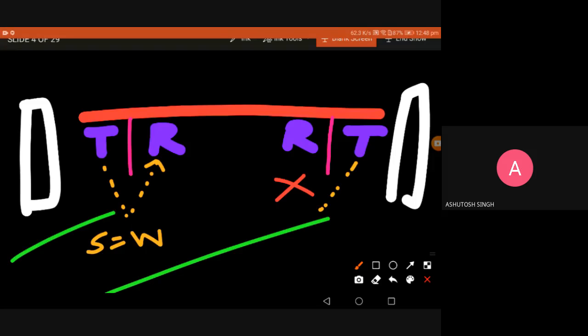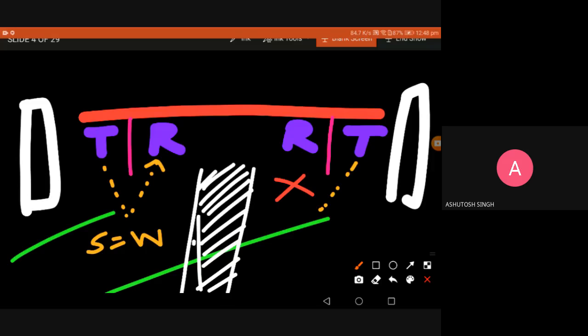So the main agenda here is whenever my line is exactly in between the two sensor modules, both sensors will sense that they are going through a black line. There is no reflection, so the receiver will not receive any radiation input or sensing. So it assumes that both sensors are flowing through a dark surface. So you can confidently go forward, rotating both the motors in the forward direction, or in the reverse direction, based on the application.